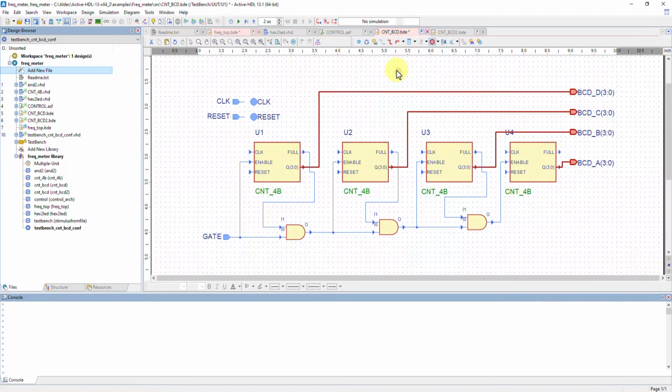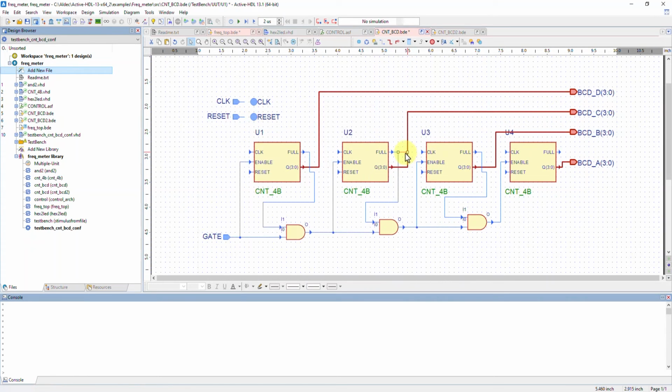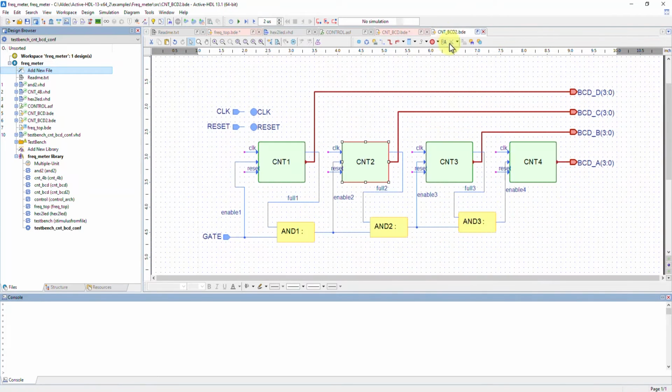As a little side note, you can connect wires to buses to create bus taps. Just connect a wire to a bus and be sure to label the bus taps appropriately relative to the bus label and size. If your block diagram needs additional HDL statements, you can click on this icon here to add HDL statements like the unit header, generics or parameters, and more.